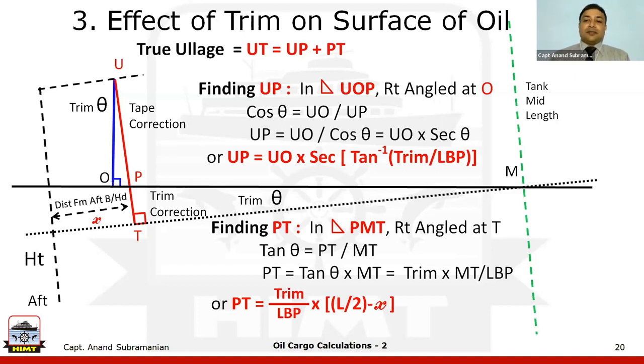Is it clear? Sir, are ullage tapes and sounding tapes different, or both the same? Both are the same in the respect that both are suspended from the top. They're suspended from this point U, and they both use gravity to go down. But in the sounding tape, it is going all the way down. Have you seen those engineers when they're using a sounding tape to find out the ullage of the bunker tank?